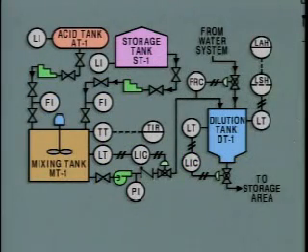The last group of instruments we'll look at is associated with the dilution tank. This symbol, labeled FRC, represents a local flow recording controller that measures and records flow from the mixing tank and adjusts the flow of water from the water system into the dilution tank.